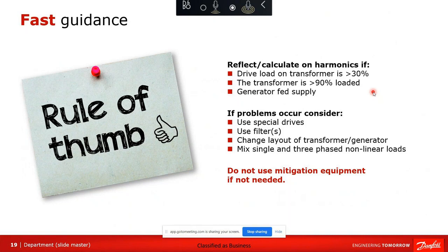So, trying to save energy, then... Yep. I would err on the side of safety in that case and use the lower rating. It doesn't take a whole lot of mitigation systems to bring things into line. And again, if you're higher loaded, but your voltage distortion is still in that 5%, 8% range, I think you'd be fine.